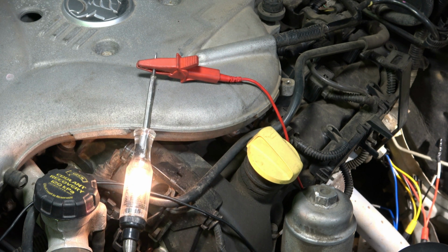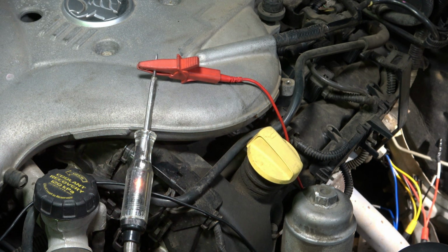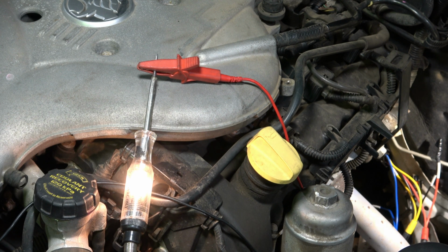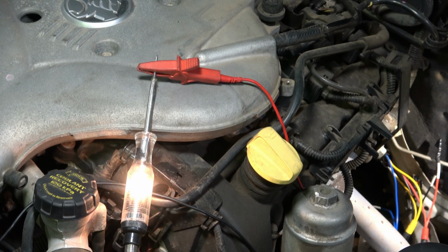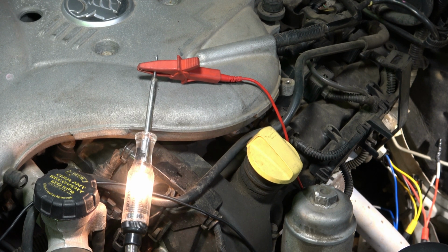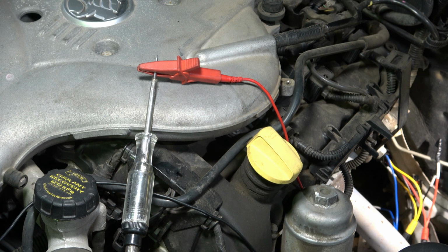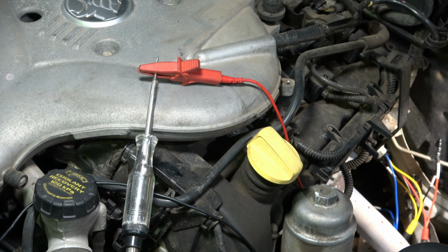Alright guys, I just started the car, and you can see that test light blinking on the heater circuit wiring. What that means is the blinking part, it's a duty cycle type heater circuit, so we know it's working. Now we know the heater circuit, the power and earth are there for the heater. I'm happy with the heater circuit. Now let's move on to our oxygen sensor side.